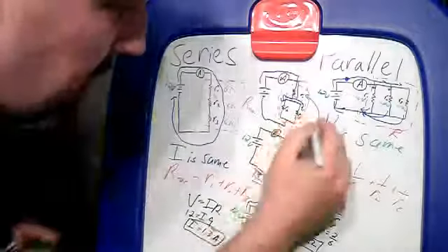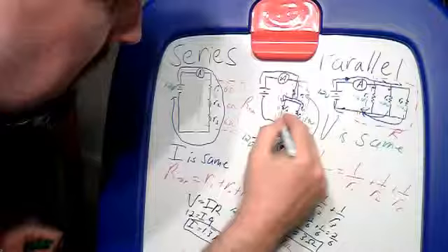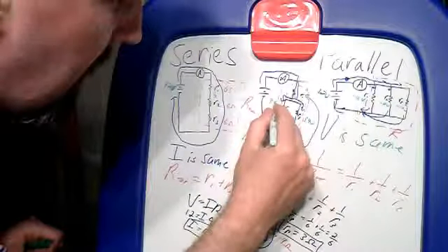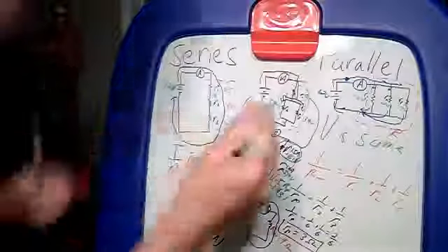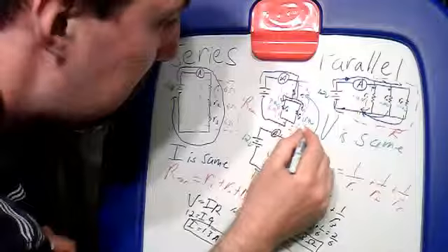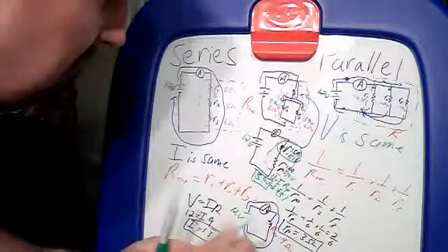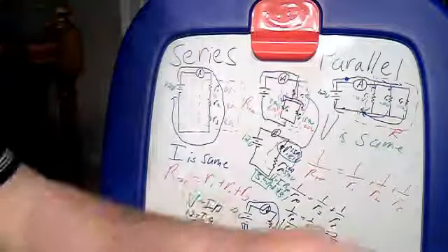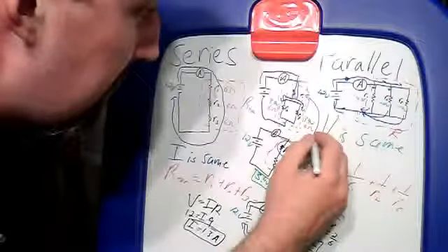So we now know for R3 we have a 3.9 volt drop, and for R2 we have a 3.9 volt drop. And if we know these resistors are each 6 ohms, we can then figure out the current. So we could say Ohm's law again, and we're running out of room, so let's do it right over here.